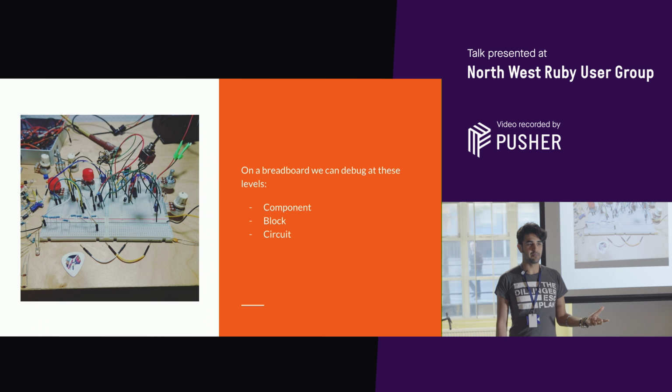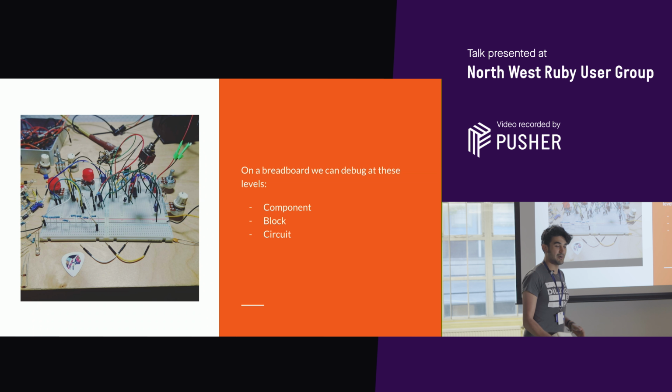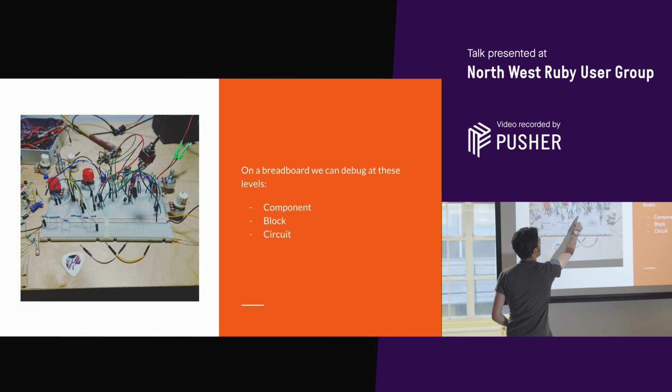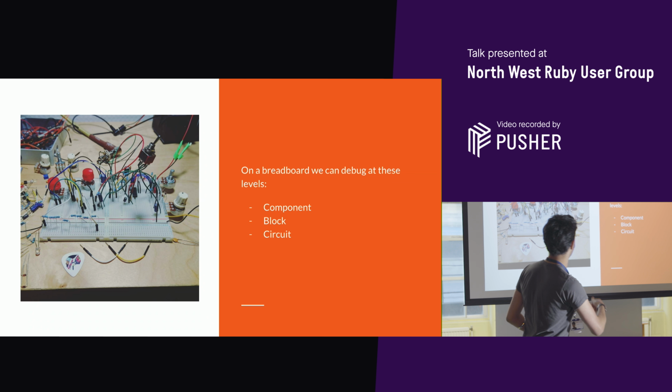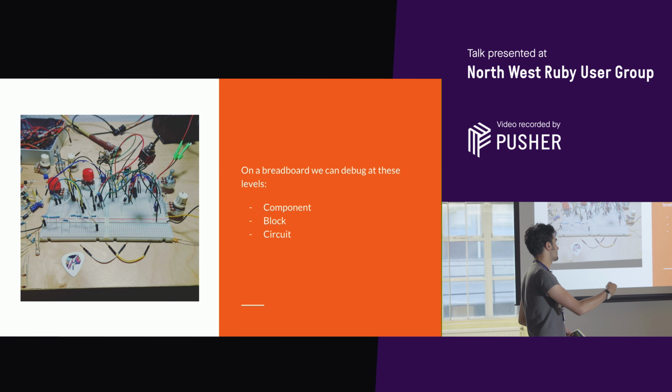And the great thing about a breadboard is you can debug it at multiple levels. You can debug it at the components. So when I was picking on Brandon earlier, I said, how would you test that capacitor? So again, this guy here is also represented on this circuit. We can see multiple capacitors. I can test them at the component. I can literally take them out of the breadboard, test them with a multimeter, put them back in if they work. If it doesn't work, I can switch in a new one.